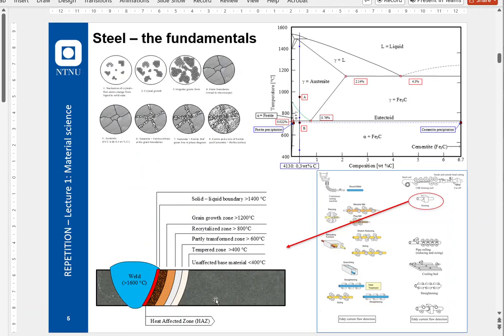We talked about the steel and how it goes from a melt to a physical form, and how grains change even in the physical state when steel has been changing through its phase diagram. Now, what is also taking place is changes at room temperature. Only they are extremely slow compared to when you heat it up.